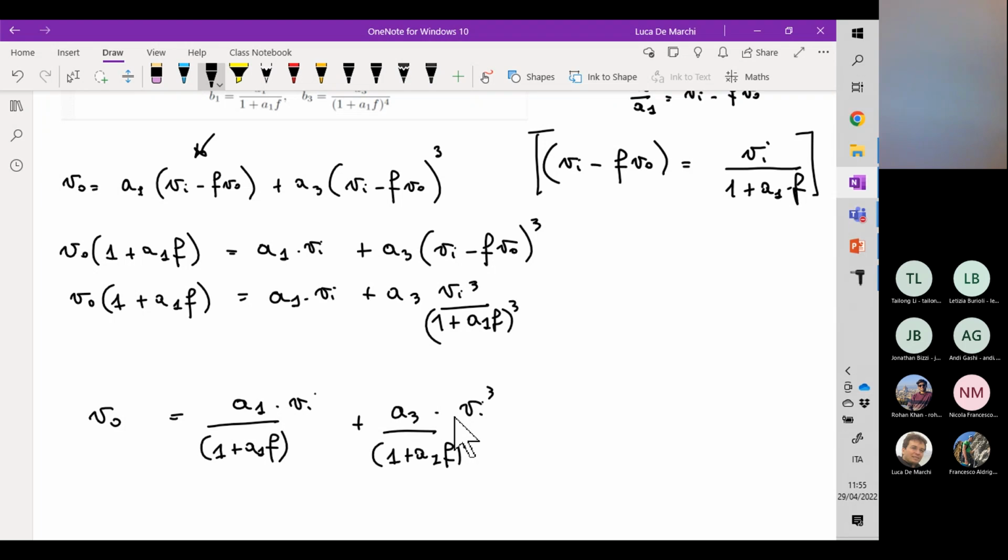So now we indeed do have a voltage drop over Z out because we are not considering the circuit in open condition, let's say RL equal to infinity. So there is some current flowing here. And when we do have some current, V out is given by A times VE plus the voltage drop over Z out.